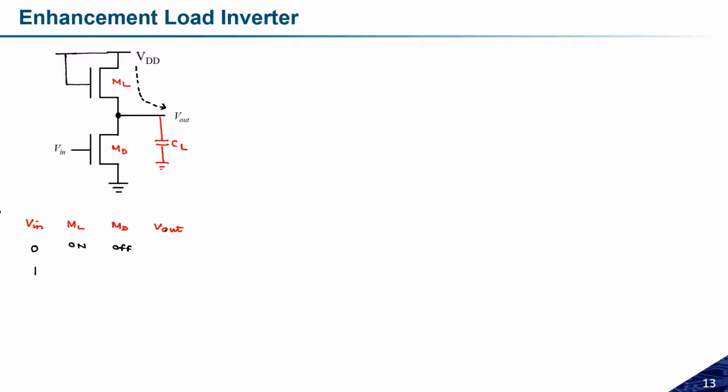But the important thing is, because at the load side we have used an NMOS transistor, and we want to pass logic high by using this NMOS transistor, we know that the NMOS transistor is weak at passing high, so it cannot pass logic high completely. There will be a threshold voltage drop. So at the output we will get a threshold voltage drop.